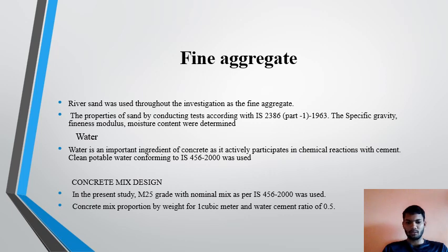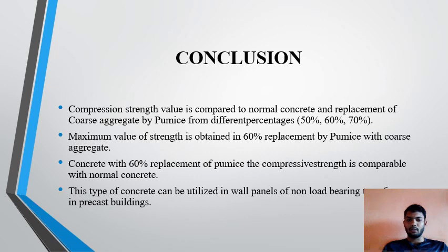Water is the important ingredient of concrete, active in chemical reactions with the cement. Potable water conforming to IS 456 2000 was used. Concrete mix design: in the present study, M25 grade with nominal mix as per IS 456 2000 was used. Concrete mix proportion by weight per cubic meter and water cement ratio of 0.5.